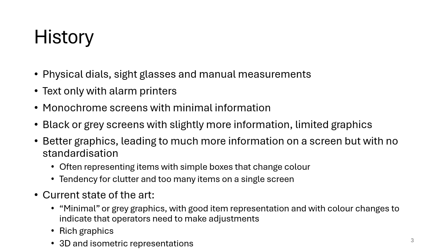So we might start off with grey, maybe a slightly different shade of grey to indicate everything is normal. Then that might change color to maybe blue for something is required to operate on but not urgent. And then you may get alarm colors like orange for attention needed, and red could be an urgent state. Even that's problematic though, because you get problems where different colors can mean different things to different people.